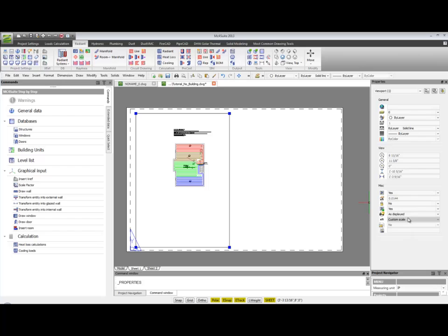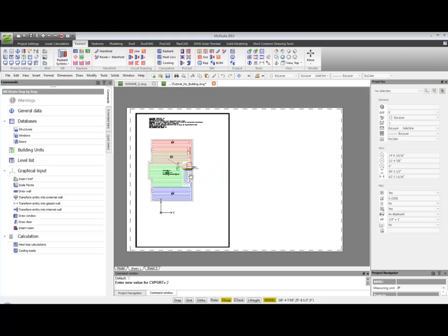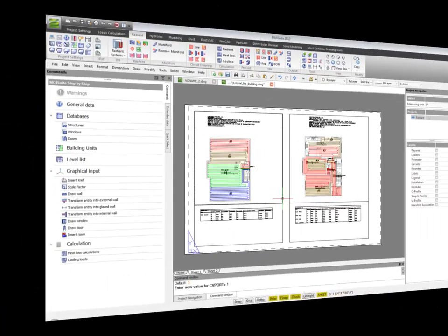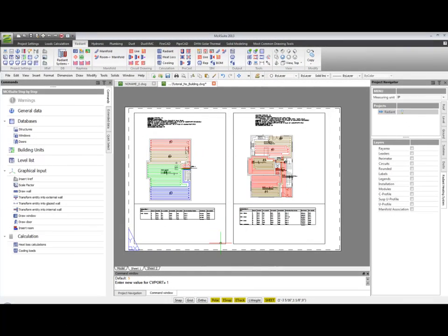In the Properties tab of the viewport, it's possible to set the scale factor. Let's use 1/4 to 1 foot or 1/8 to 1 foot. Select the scale factor that best fits your needs. By arranging 4 different viewports, it's possible to plot both levels and both tables in the same page. It's also possible to add any other information you need to add.